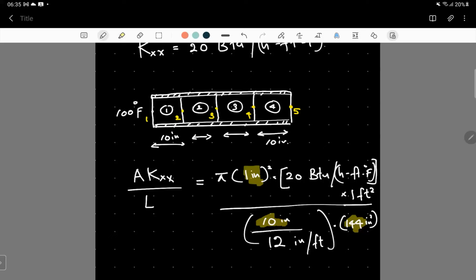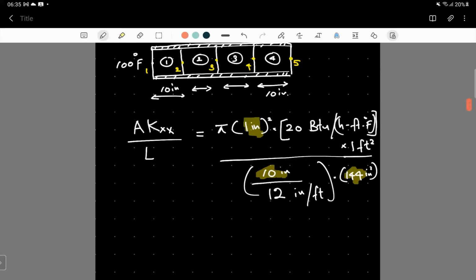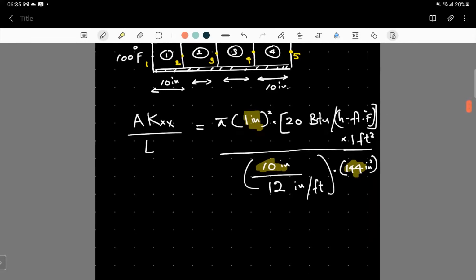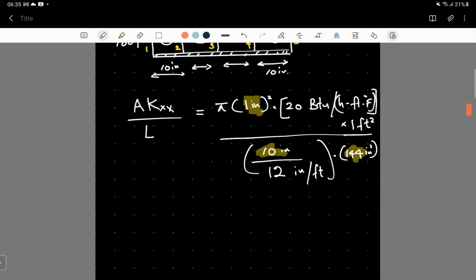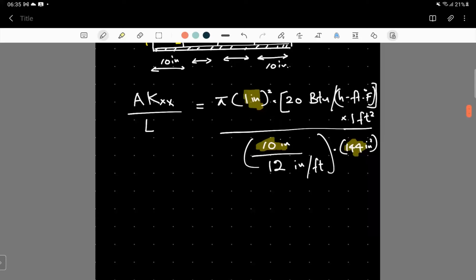Next, the fundamental component which we require to formulate the finite element problem is the convective contribution. For the moment, let's write it and keep it if not necessary. Let's not use it, since it's the first example. If there's a convective term, the common factor would be the convective heat transfer coefficient, the perimeter times the length of the element divided by 6, which is the common factor for such elements.